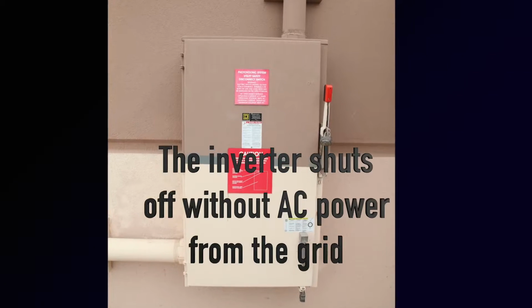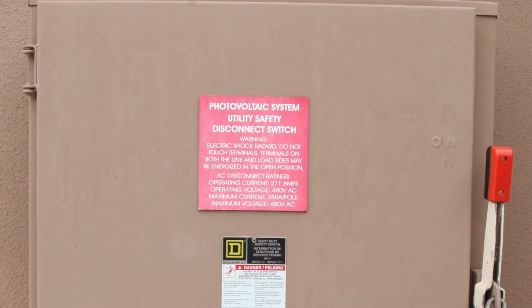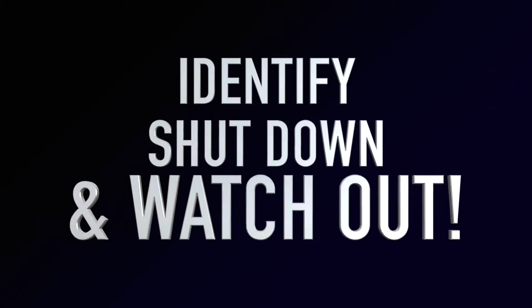The most important thing from a safety perspective to understand about inverters is that they need AC power from the grid to run. So if all you do is shut off their AC power source, the inverters will shut off. Now we'll focus more on this later, but for right now, just remember that to make the system safer, we do want to shut the inverters off.